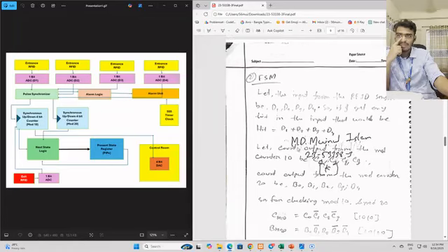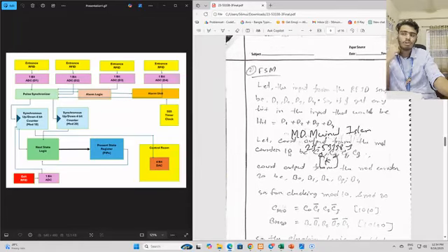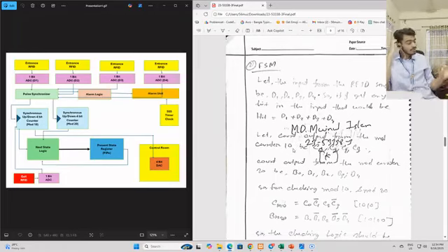Fine. Then we need the count output from the mod counter. We have logic that more than 10 people cannot stay on the platform at a time. So if the platform passenger count is 10, we cannot let anyone into the metro station. Also, only 20 tickets are issued. So if the ticket count is already 20 and someone is trying to enter again, that means someone is trying to do fraudulent activities or something like that, because only 20 tickets are issued by the authority.